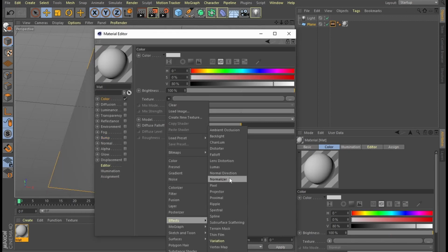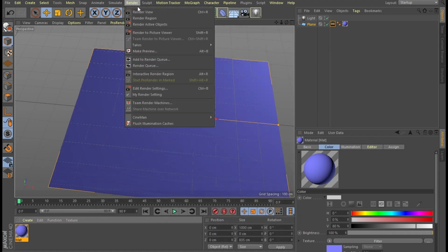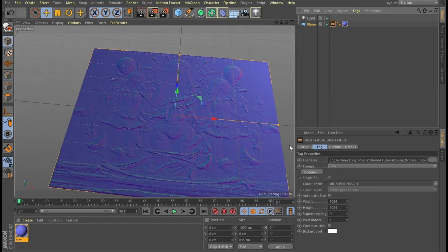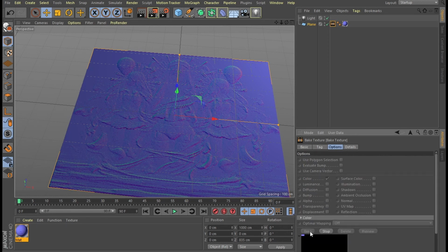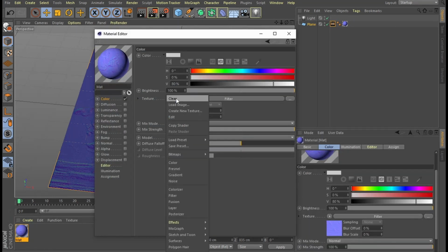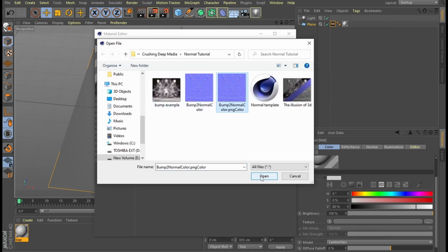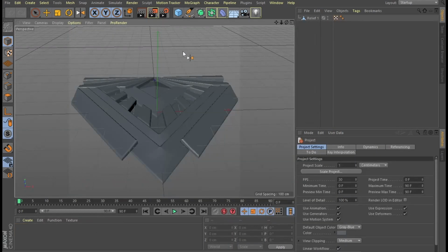If you have a bump map for your design but need a normal map, you'll be able to make one easily by baking the bump map into a normal map in your rendering software, like you see here, to get even better results. If you just Google how to do that on whatever software you're using, you should find numerous tutorials, but if for whatever reason you can't get that working, the method I'm about to show you for making normals from geometry can also be used on planes with a bump map applied. So now that that's out of the way, let's get started on a simple setup.